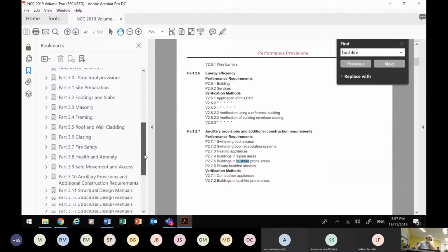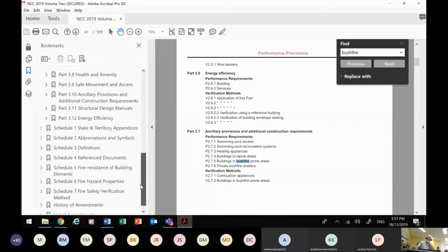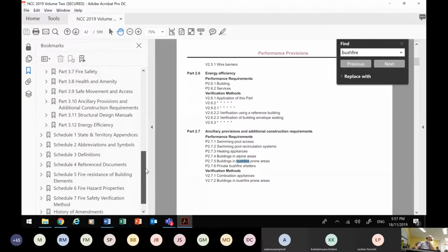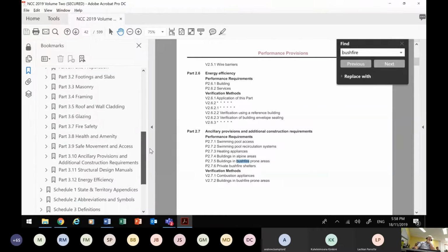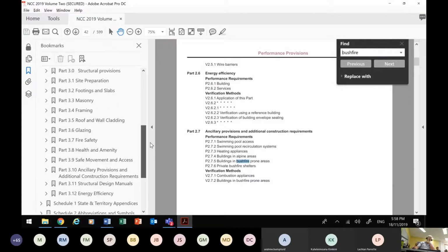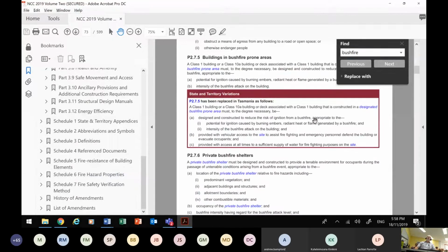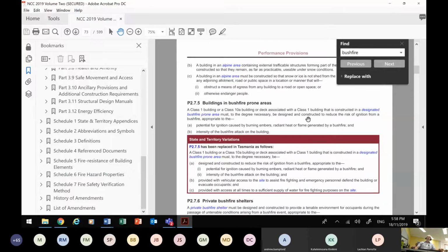And so you can see here with the National Construction Code that because I've been around a fair while, and Brett and some of the others have in building as well, we would remember before a lot of this information was in. And now I know from after probably the 2000s, 2002 or something, some rules came in which said you have to, for example, have metal fly screens on the outside of your windows if you're in a building in a bushfire area, and all sorts of things like that. So let's just have a little look at what some of the things the code says.